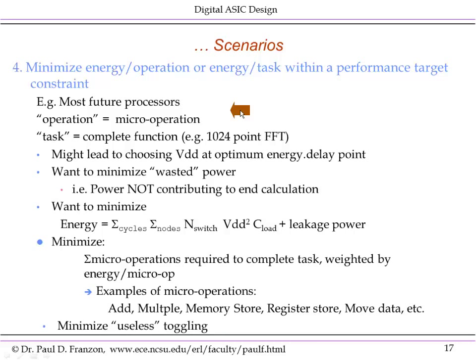That's why we're going to all this effort to write all this RTL and so on. So the question then becomes, how do you as a designer maintain a high performance, which means a reasonably high VDD, say 0.6, 0.8, or maybe 1 or 1.2 volts, and a reasonably high clock frequency, say 500 megahertz, 1 gigahertz, while minimizing the energy required to do a logic operation.